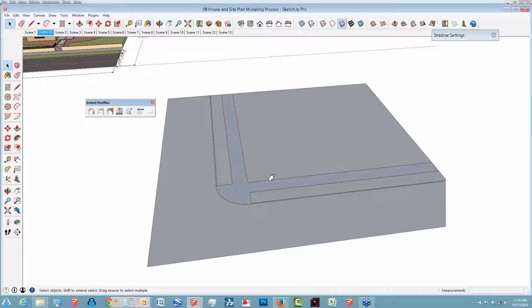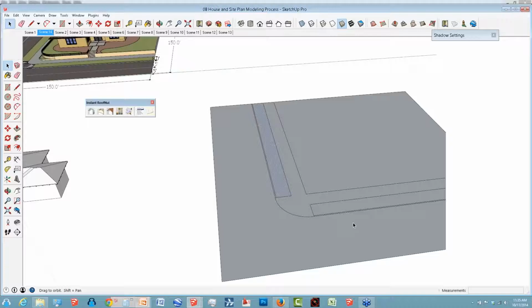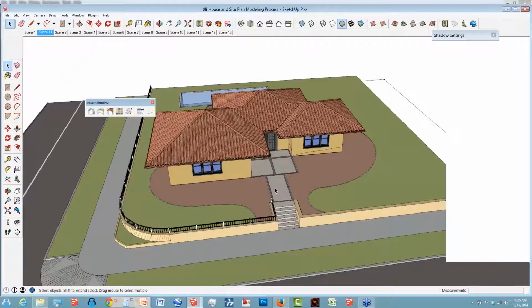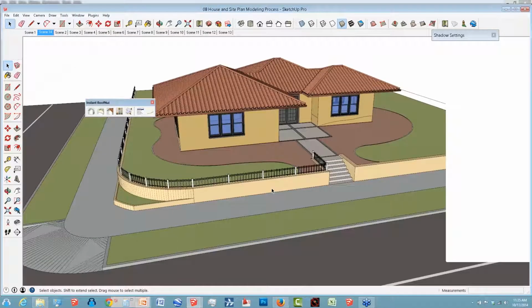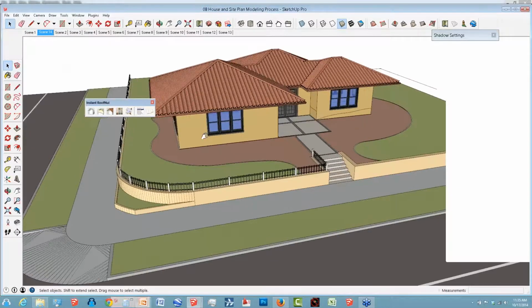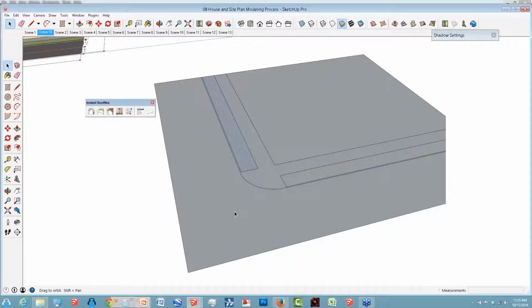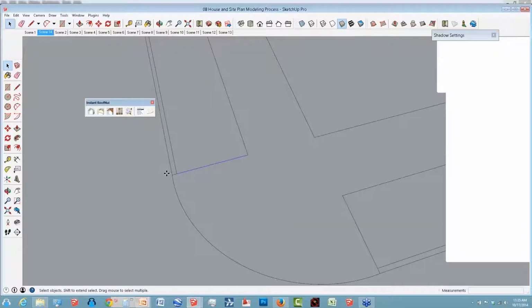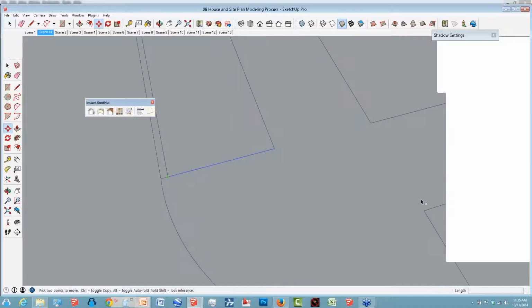We're going to keep going here, because our goal is to mimic what I created here, which will let my screen catch up to what I'm showing you. There you go. So I'm redrafting this. Because we have a curb ramp in this area, this is where you have to put your landscape architecture hat on and ask, what details do I need here? I'm going to select this edge. I'm using something called the move tool. I'm copying it over 6 inches. That's going to be my curb return.